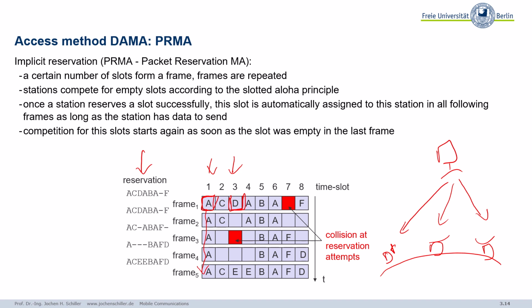So you always have a time slot in the uplink within a frame, and you have a reservation list or reservation vector on the downlink. You see this alternating pattern: you get a reservation list on the downlink and you have a frame in the uplink. This can be done in an FDD scheme on different frequencies, so this runs in parallel. Okay, so now let's have a look at the reservation list before we come back to how we get a time slot.